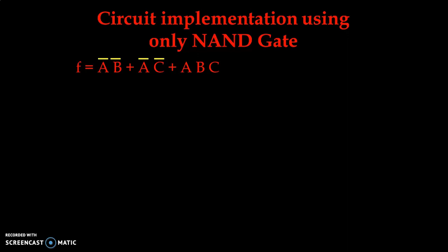When we use NAND gates, one thing should be very clear: it is applicable to SOP type of function. Here we can see that we have three product terms, A bar dot B bar, A bar dot C bar, and A dot B dot C, added with a plus sign. So it is an SOP type of function. It is not a standard SOP, but it should be SOP.